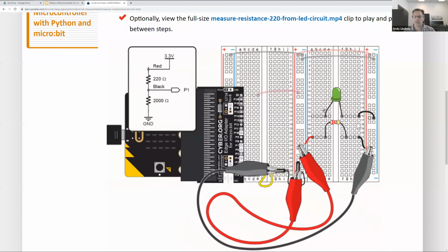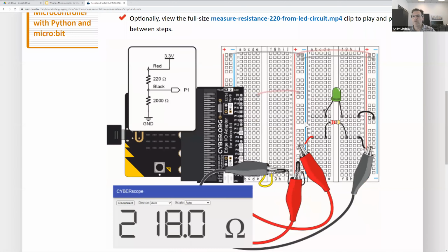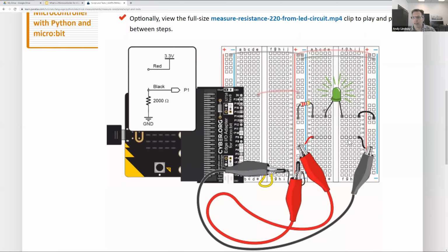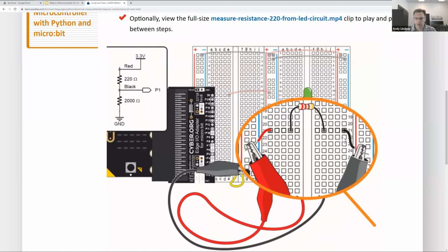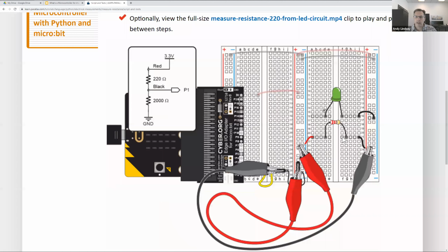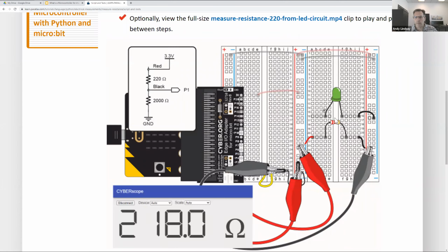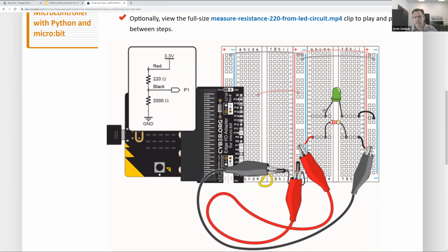And you'll be able to measure resistance. The way resistance is measured is by removing the resistor from the circuit and then probing each end of that resistor. That's a very important thing to get across to the students. I have unfortunately met engineering students who have recently graduated from a university, have appeared at a new place on the job, and they're probing the resistor inside the circuit and not understanding why they're getting a resistance measurement so wildly different from the expected value of the resistor.